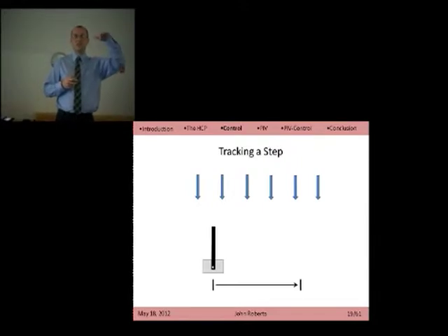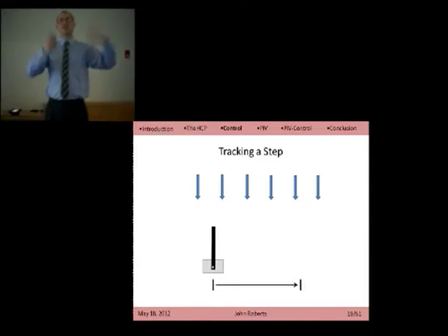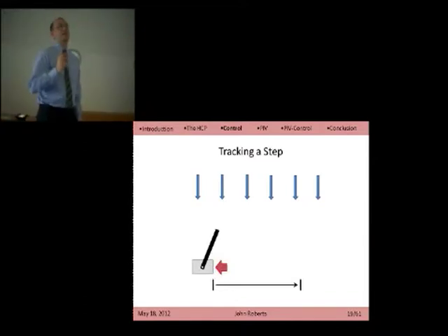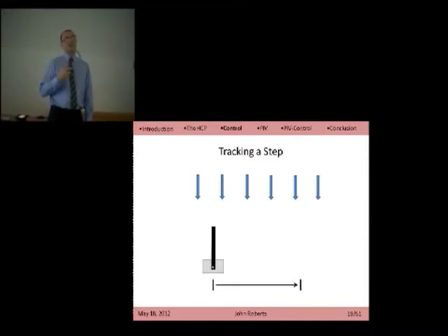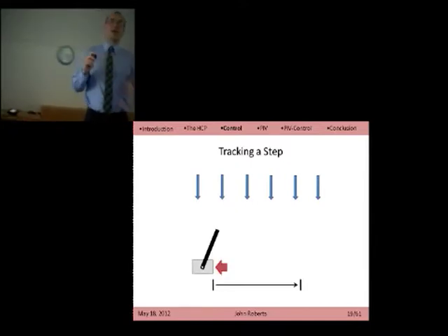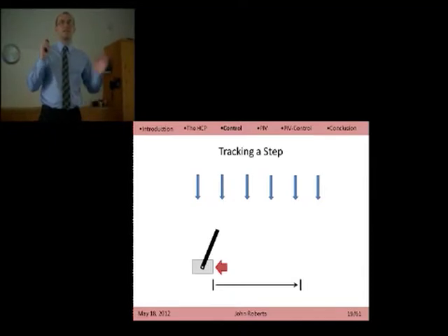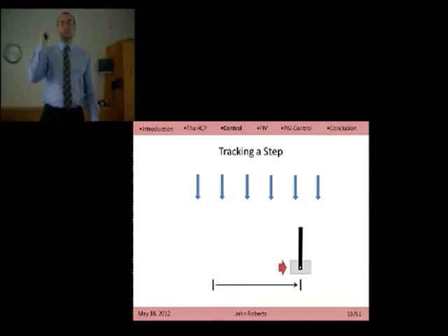For example, if it was running at a tree branch and you want to sort of jump up and point the same direction, but be at a slightly different altitude, this could be an analogous kind of task. What's cool about this is because of the underactuation, you can't just drive straight to where you want to be. You actually have to take into account the coupling between these degrees of freedom. So here we can bounce the cart backwards, in the direction you don't want to go. The pole starts falling over, and then because it's falling over, you can stabilize the pole by moving to where you do want to go.